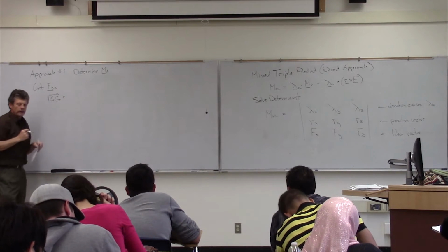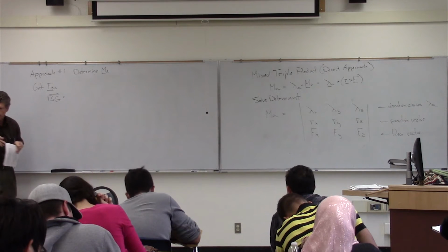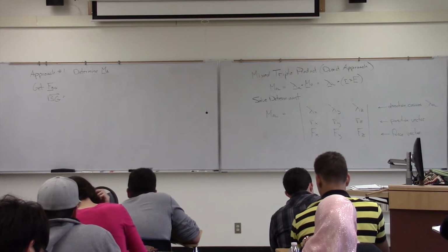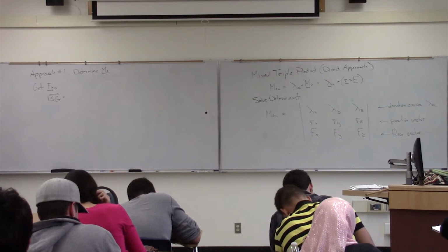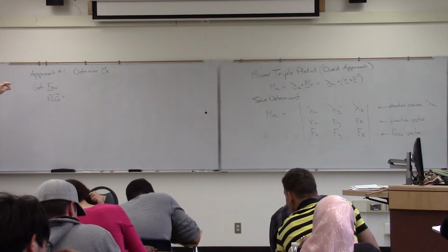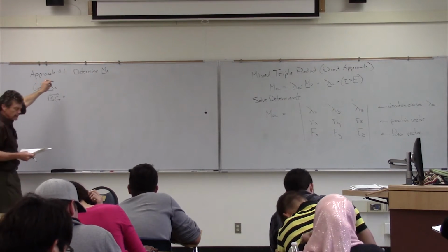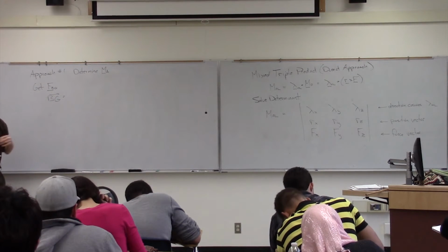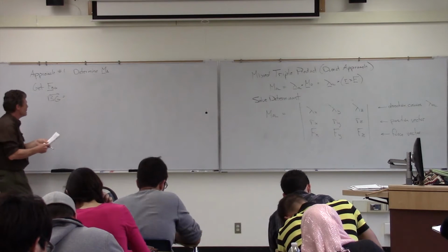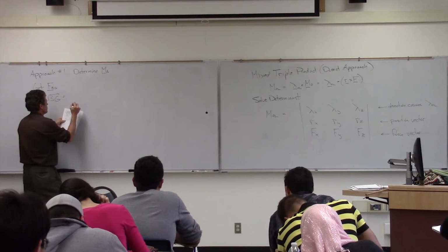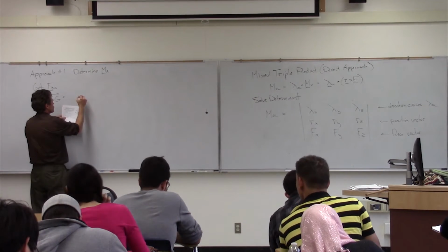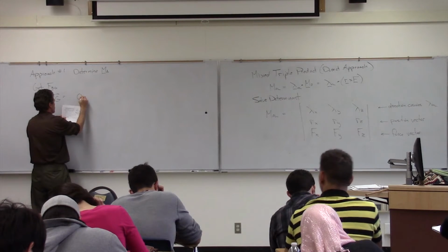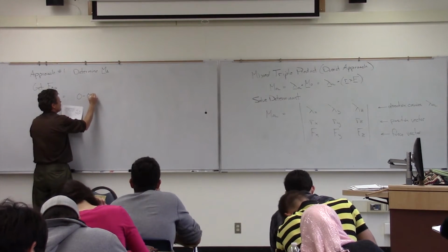So the first thing we need to do is solve for this force, FBG. So we're going to go through it. It's a two-step process. We're going to look at 2 points, and we're going to figure out that unit vector in the direction B to G. And then we're going to multiply times that force of 450 newtons. So BG, we'll think about it in terms of the x direction there. From G, it starts at 0 in the x direction and goes out to 5.